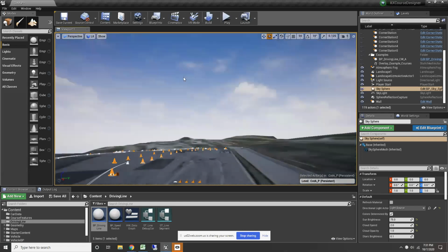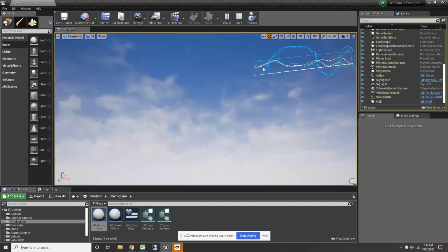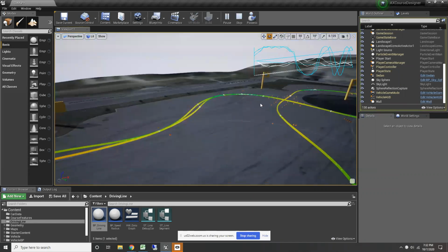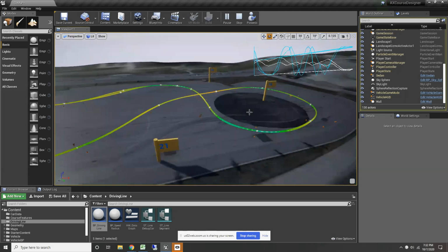And so one of the things I can do from this is I can get some decent data. I've got some rough simulations of car physics. Really what I can do is I can simulate the traction circle to a degree. If we know a car can corner at a particular G-force, like if a car can corner at 1.2 Gs, we can actually calculate for a given turning radius how fast that car might be going. And so I've baked that into this program so that we can hit some buttons, and what I can see at a very slow frame rate is a little color-coded heat map for how fast cars will be traveling in different sections of the course.